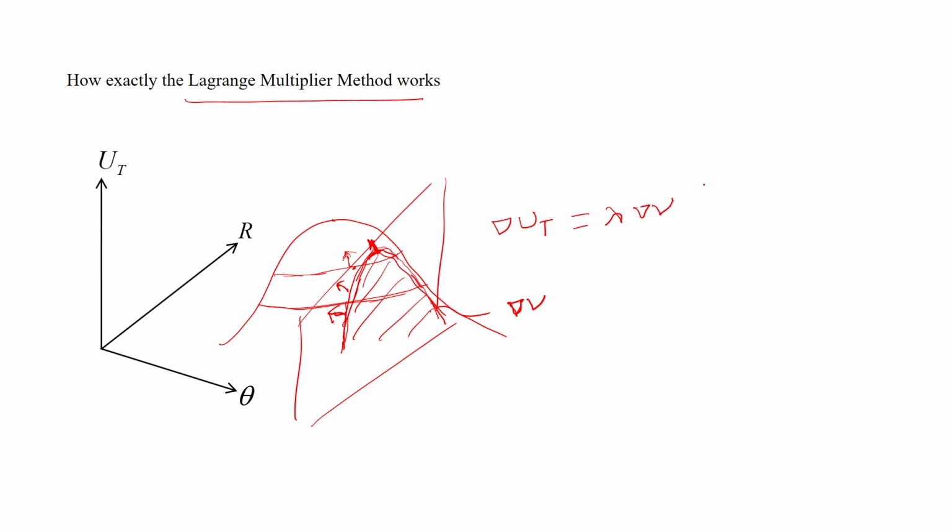When you do that, delta of Ut minus lambda times v is equal to 0. So, it is from that concept that, for this constrained energy minimization or constrained optimization, we can use the Lagrange multiplier method, where this lambda is that particular constant which is called the Lagrange multiplier.